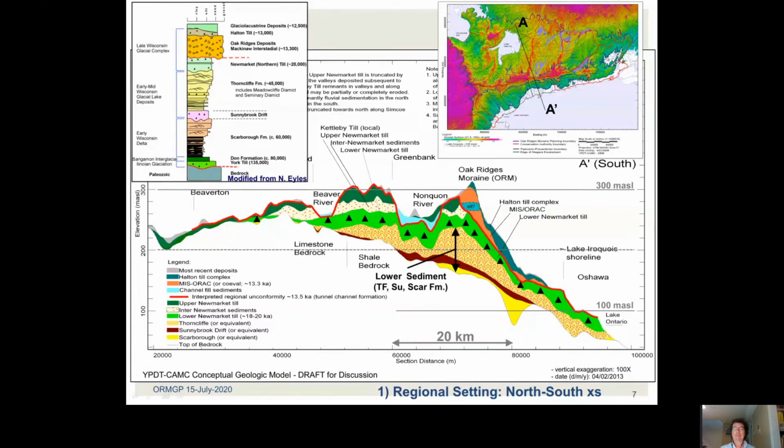Okay, so think, I guess, rivers flowing off of the uplands into a large lake. That lake is varying its water level. And then there may be a glacial component in here, a proglacial, beneath the glacier, subglacial component to that, but we're looking at extensive lacustrine deposits in here. And again, think for grain size, think proximal distal, close to a sediment source, coarser grain, sands and gravels. Distal from a sediment source, which could be a river, think silts and clays.